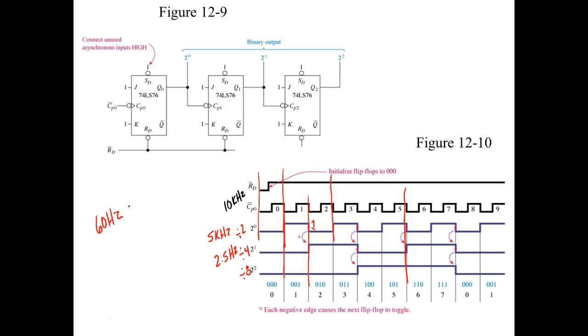So what we wanted to do was make a digital clock. Well, the problem is this is 60 cycles per second, and I needed what? I needed 1 cycle per second. So I just figured out how to use counters to get a divide by 60. And it wasn't bad. So I came in with the same circuit that we hooked up before.